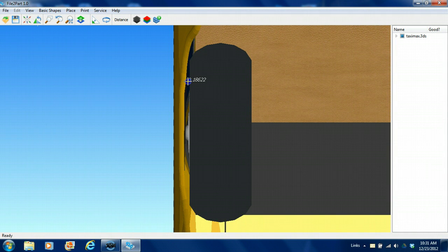The smallest distance is about 1.3 millimeters. So we want to add about 1.5 millimeters in order to make sure that the wheel is going to be attached to the body of the car. Make sure we're measuring distance on a screen, so we want to be very careful positioning the part that you want to measure in parallel to the screen view. When you do this, you'll get pretty accurate measurements.